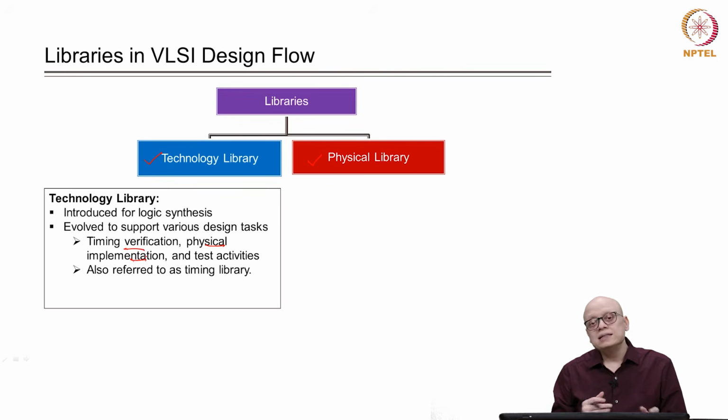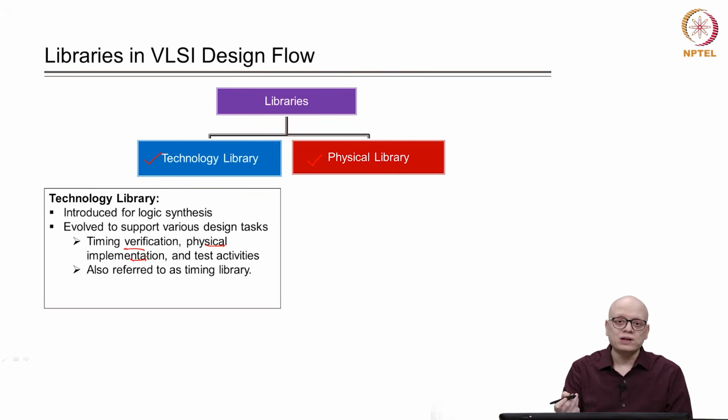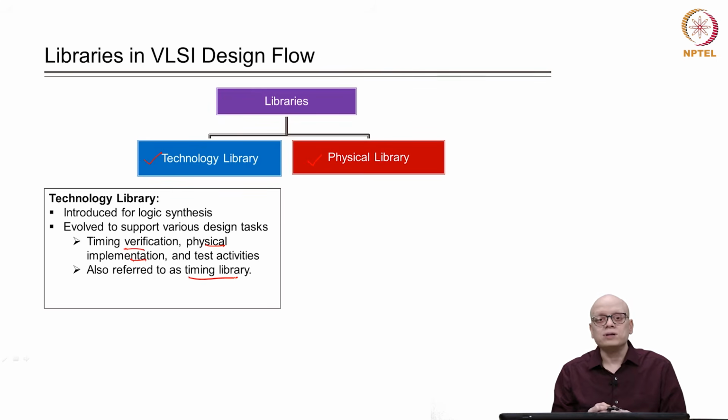And since these technology libraries contain primarily the timing data, sometimes we also call them timing libraries, but keep in mind that the technology library also contains information on power and much other information that we will see subsequently in this lecture.